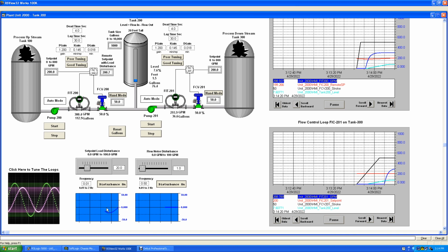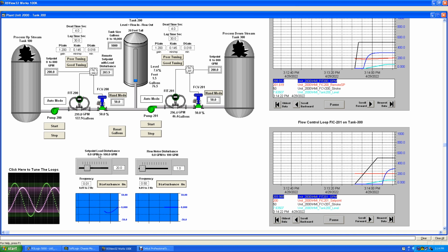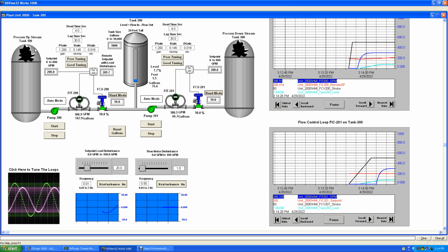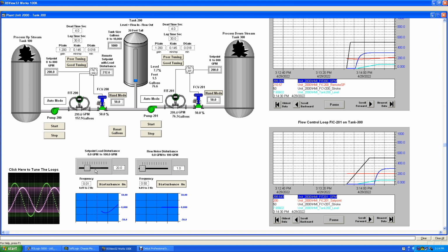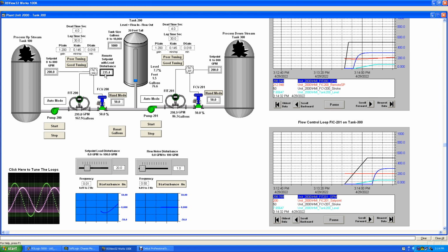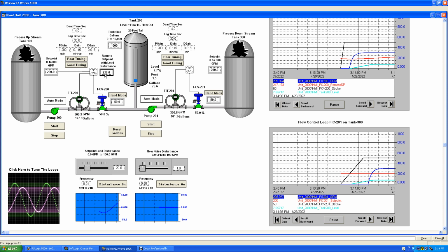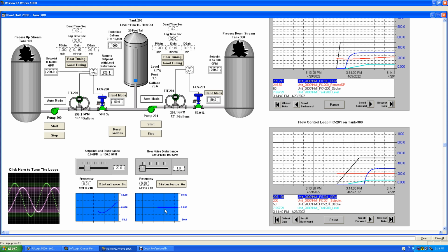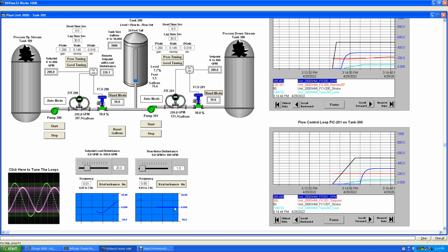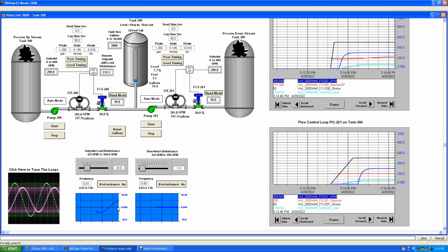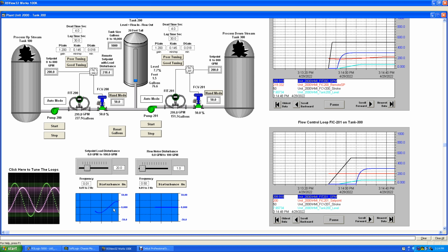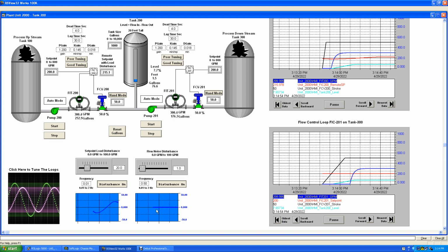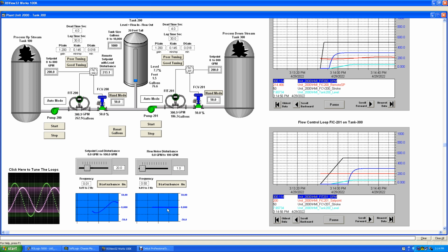And you can see the noise right here in the set point. This is a load disturbance coming out of the process upstream, and the load disturbance in gallons per minute. You can see the set point changing based on the load disturbance of the gallons per minute. This here has a disturbance on the bottom too. You'll see the noise right here. These are what the function generators are doing. The function generators are making these sine waves right here. And this is a sine wave as well. And it's just a really small amplitude.